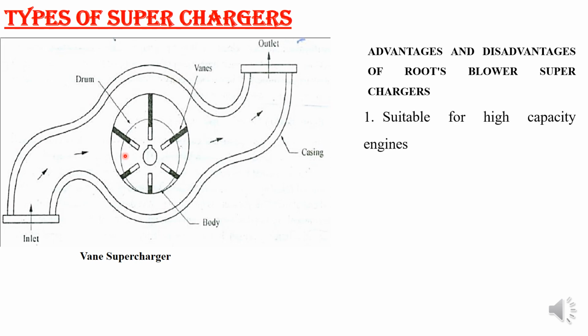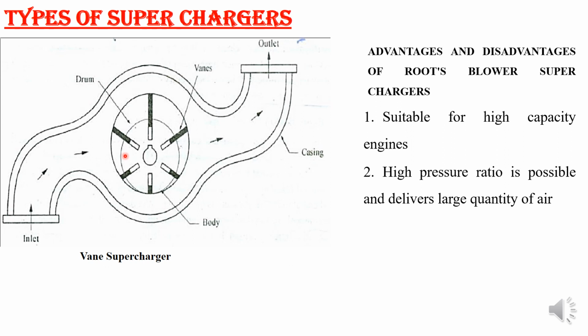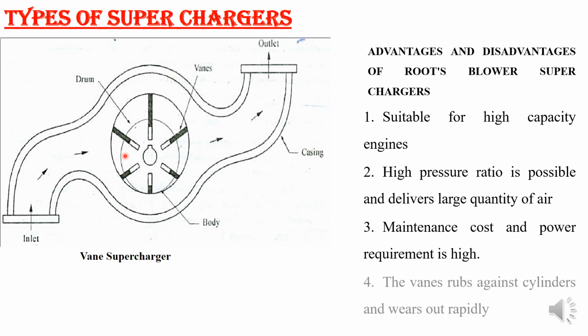So it is suitable for high capacity engines. High pressure ratio is possible and it delivers a large quantity of air, but maintenance cost and power requirement are high. The vanes rub against the cylinder and wear out rapidly. So the first two are advantages, the next two are disadvantages.